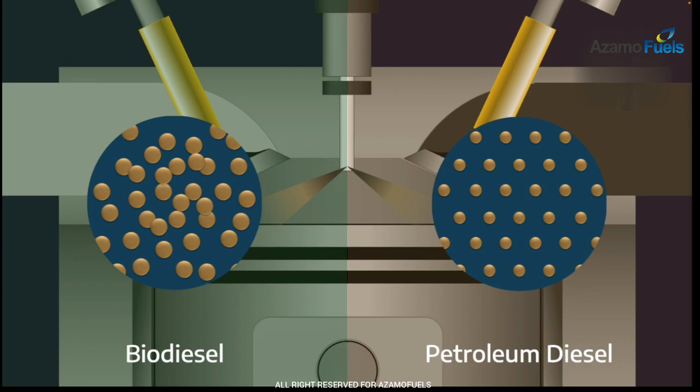So what does that mean for our lubricant? Well, when we get less atomization of the fuel, that means that in local areas, we would say that it is fuel rich, right? And so we're entering a rich burn environment. When that happens, we typically have more incomplete combustion, and the product of incomplete combustion is soot. So generally, when we're burning a biodiesel, we end up with more soot in the crankcase, right?